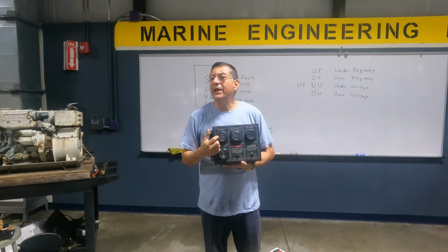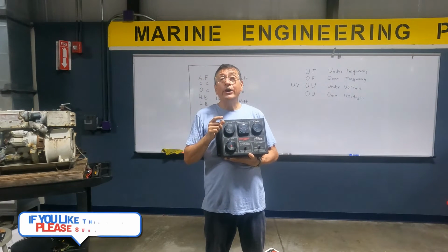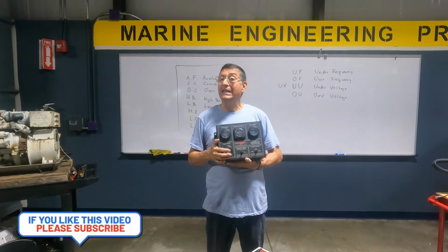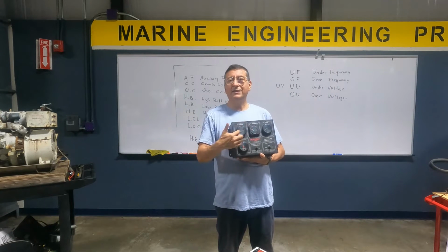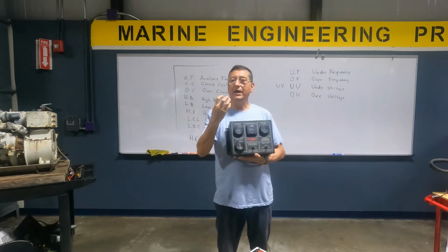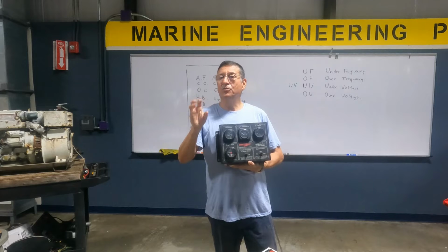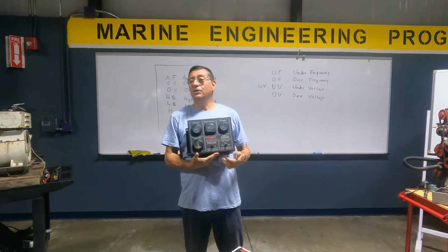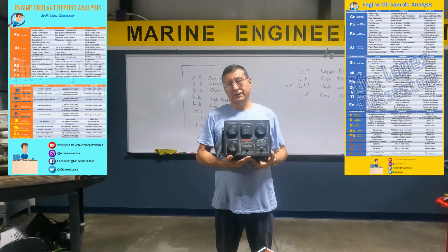Excuse me, the oil pressure, is the needle of the oil pressure exactly in the position that it normally is? No, it's a little low, Mr. Lopez. All right. You have a big issue in your motor and the oil pressure decreased. If you have low oil pressure and high temperature at the same time, you have a big issue in the engine, and you need to call an expert in engines. Probably he will take a sample of oil and send it to the laboratory, and with that sample you can discover where the problem is. I am going to explain that procedure using my poster about the analysis of the oil, analysis of the coolant. All right, guys?